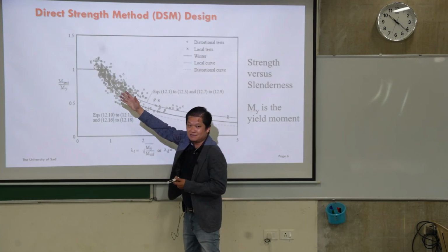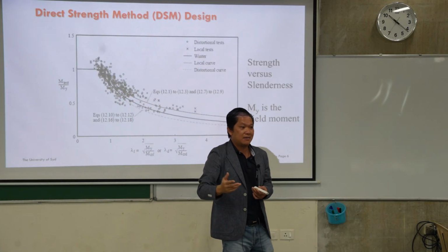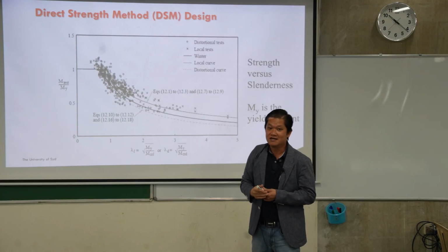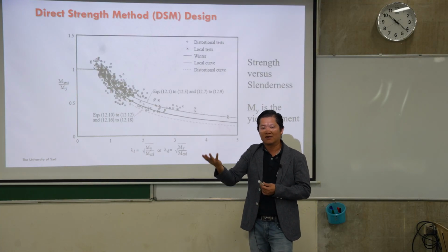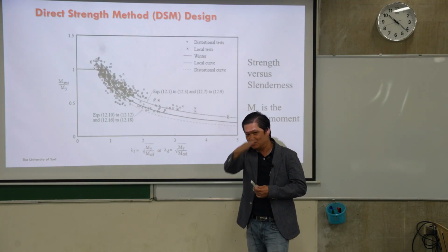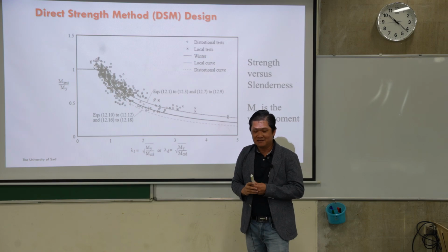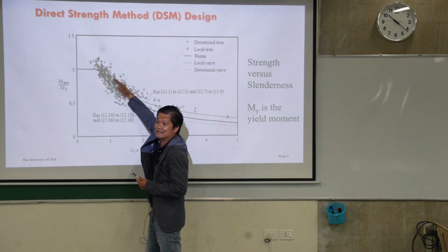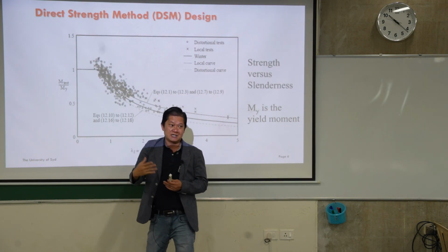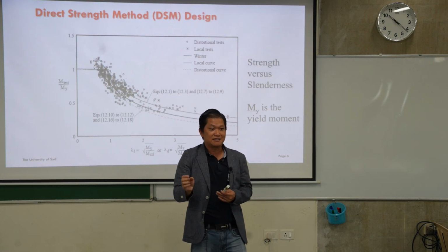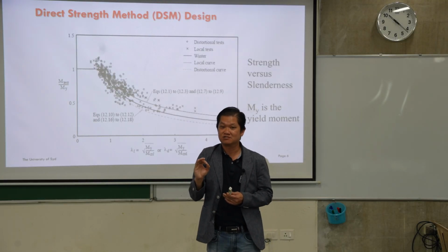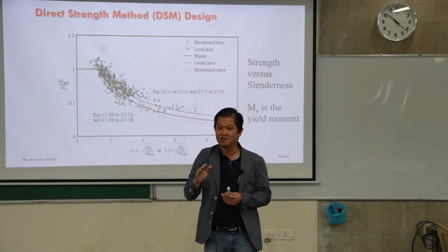But when you fit in the mean, as in the US system, of course it gives you a bit more load because you put in the mean in the middle. And then you get all the variation in here. And that variation would be taken into account in the phi factor. So the phi factor will cover all that, okay?